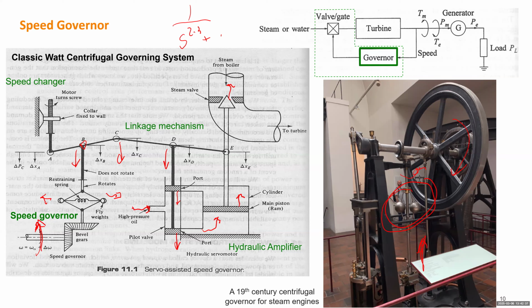This means you can use much fewer parameters to characterize the original turbine or governing system. That's just for convenience of categorizing the model. But using a fractional order system is another challenging problem. You still need to translate that back to a 100 or 200 order system for accurate representation. But I just want to give you an idea that the actual turbine or governing system can be very complex, while in stability studies we can usually reduce the order to maybe 2, 3, or 4, a very low order system.